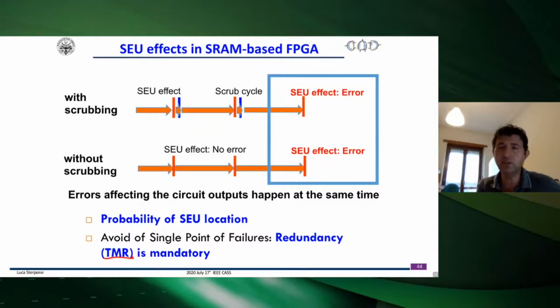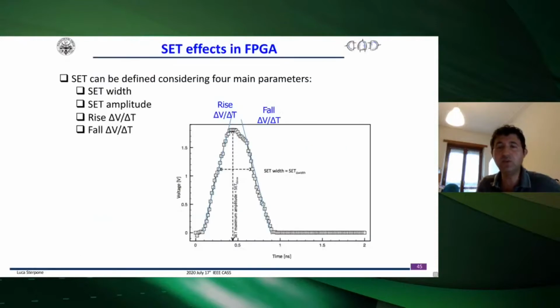Thanks to these techniques, you will triplicate your circuits and you will be able to protect the scenario of your application, as we will see in the mitigation techniques later. We understand the single event upset phenomena that may happen in a RAM cell or also in RAM memory on a flash FPGA if we have a module of RAM.